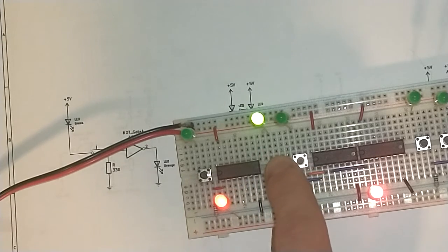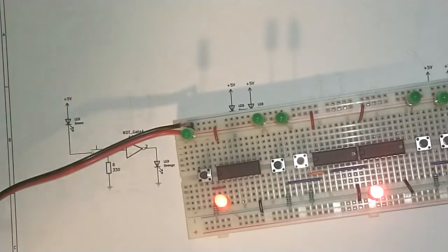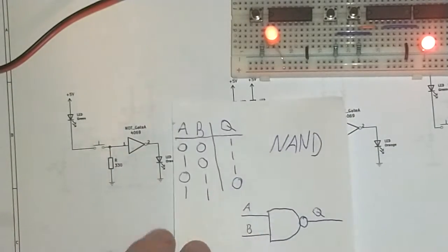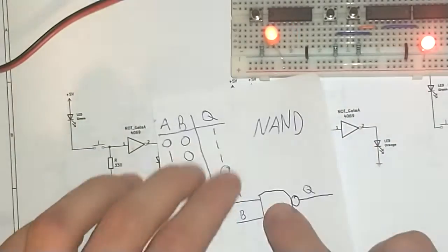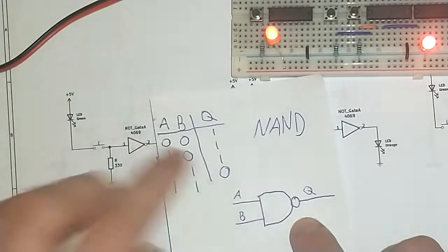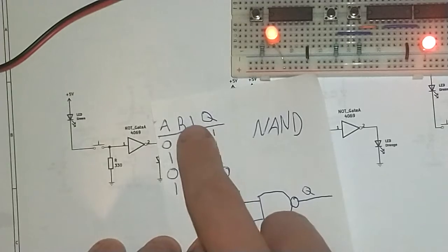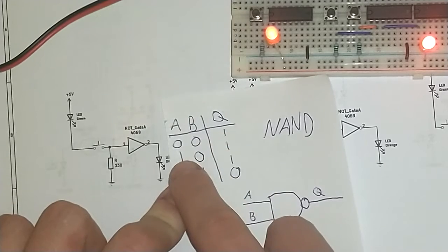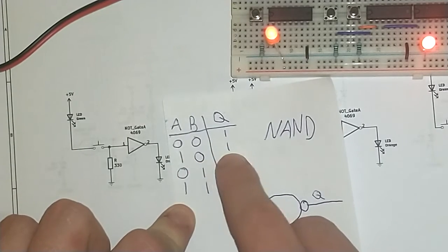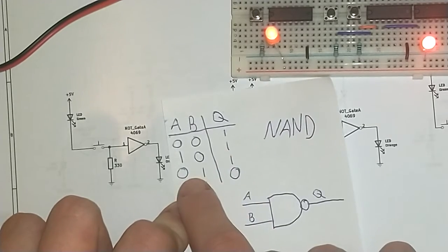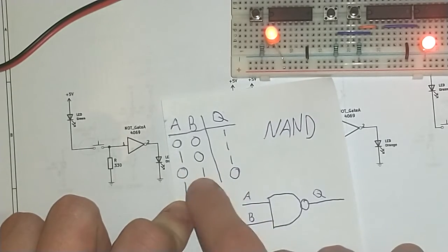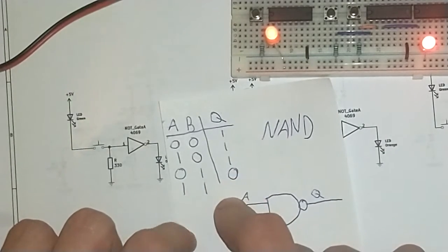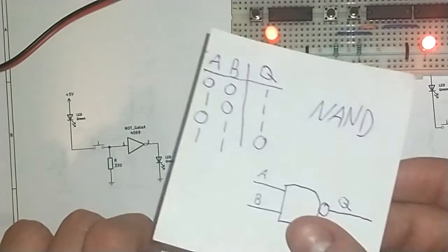And as you can see, when I turn on output, well, I should probably show you the truth table first. So yeah, this is a NAND gate. As you can see, this NOT gate turned into this little bubble over here because it has this bubble here. So it basically connected over here. When both of the inputs are low, the output is going to be high as well. When one of the inputs is high, the output is still high. Basically when both of these inputs are high, then the output is going to be low. That's what a NAND gate is,